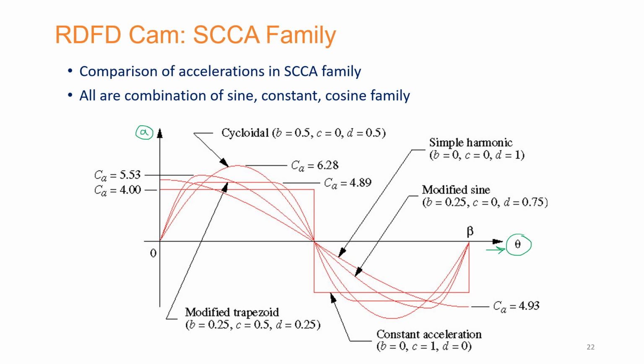So in this particular case, the very first curve that we should start our discussion with is simple harmonic, over here. So this is the simple harmonic profile that we have available. It starts from this value, and on the other side it goes all the way to this. So these are the two points from where the acceleration starts and finishes, and these are obviously finite non-zero values corresponding to acceleration.